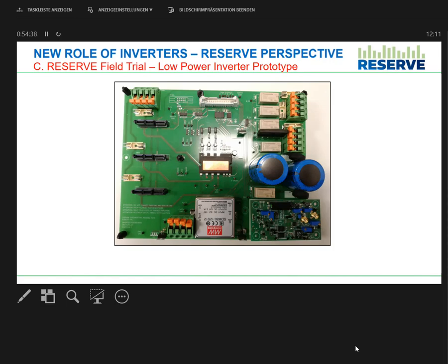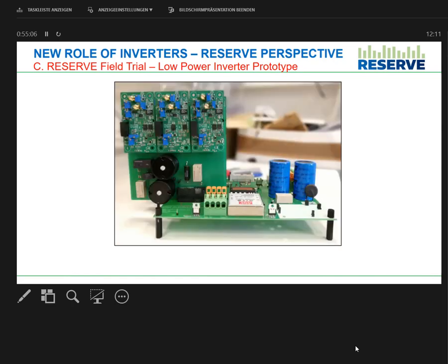And then we tried to modularize to have the LCL filters of each phase as separate cards, which can be plugged in at right angles to this plane in this board. And we also made measurement boards which can be modularized. So small high bandwidth measurement boards, because we're going to measure high bandwidth signals of currents and voltage in order to calculate the impedance. So for example, this is how the finished product looks, and now we are in the testing and commissioning process of this.